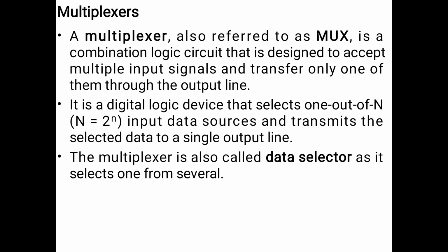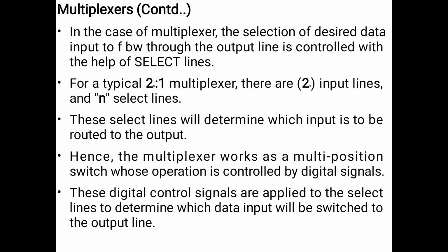A multiplexer, which is also called as MUX, is a combinational logic circuit that is designed to accept multiple input signals and transfer only one of them through the output line. It is a digital logic device that selects one out of n input data sources and transmit the selected data to a single output line. The multiplexer is also called data selector as it is selecting one from several inputs.